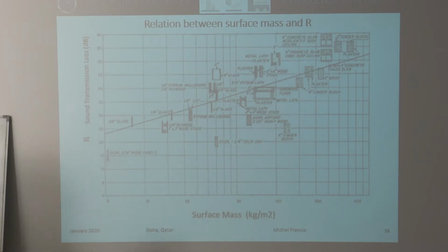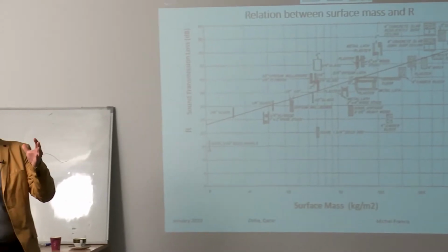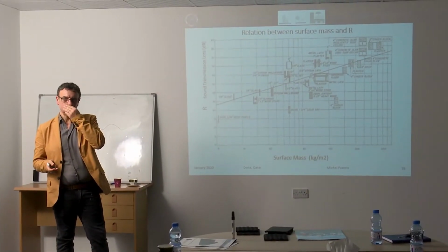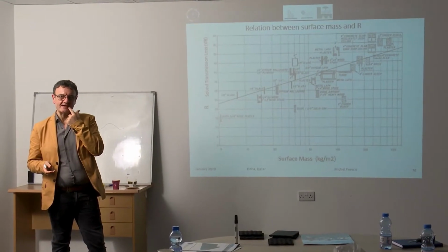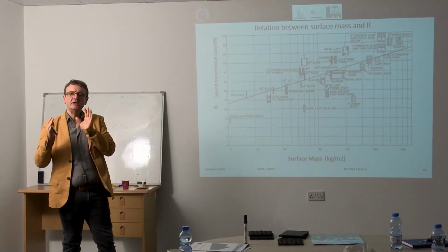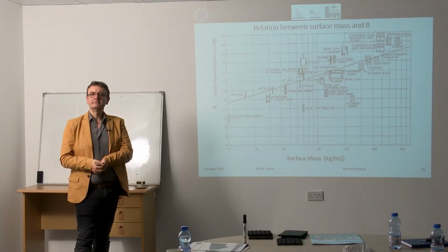So it is the density of a surface. Density is kg per cubic meter, yes, but that is the density of a surface, because we're talking about a partition. So how much mass do you have per unit of surface? The more thickness, the higher the mass per square meter, so it is better to define it in kg per square meter.